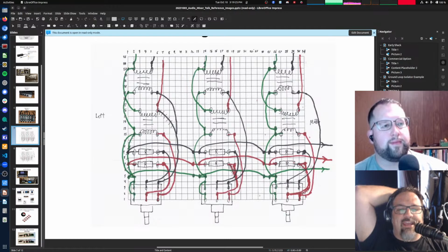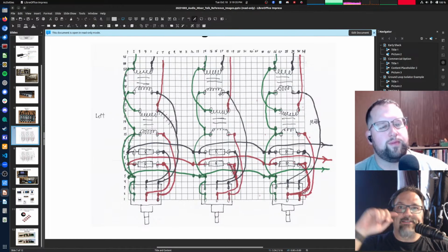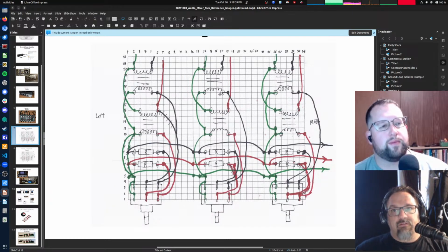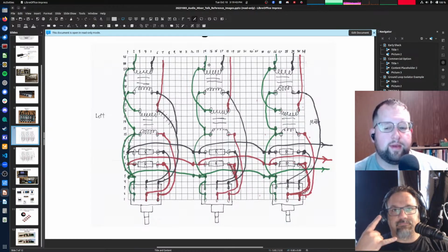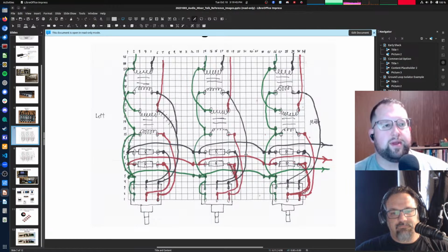But you should not have any connection between either of the pins on the input side and any of the pins on the output side. Right? Between the input side and the output side, they should be totally isolated. There should not be any connectivity between those two. Excellent. Yep, that's what I'm seeing on mine, and I'm glad to get it reinforced that that is correct. That is correct. Yes, it is.